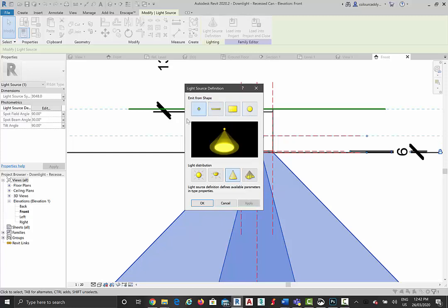Now, I know why they've left this option in here. It's because if you take this same light into 3ds Max, where you do have a lot more options for lighting, then these do make a difference. So if you bring this light in with the line setting, it will come in and then it'll work as a line. In some ways, it works partly as a line in Revit, but again, don't expect it to work like a fluorescent light or a proper circular light source. It just doesn't, unfortunately. So effectively, point is the only option you need to use.